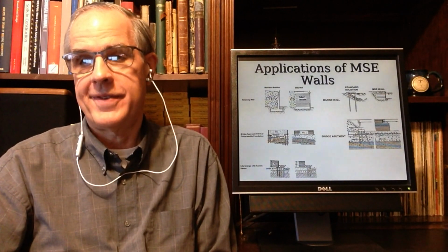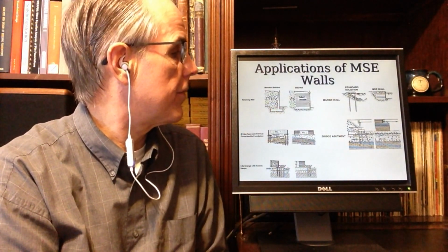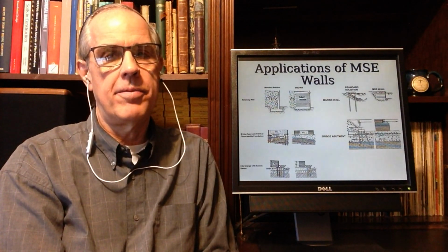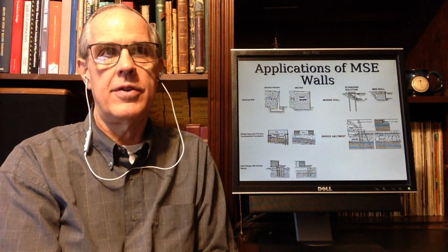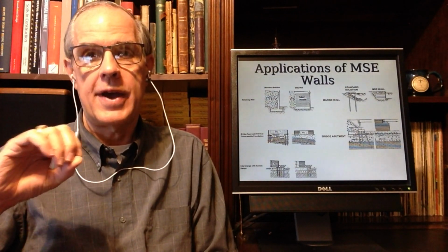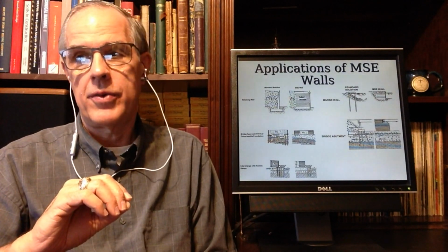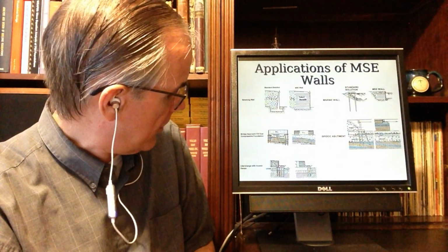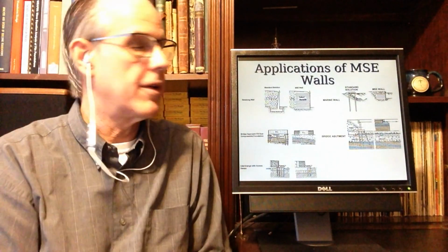Applications, of course, retaining wall. As you say up here, they can be used to replace gravity walls. Marine, I don't see that many marine applications. The biggest problem for using an MSE wall in a marine application is, it drains well. Tidal effects are not that bad. The biggest problem is going to be working in the wet, and you'll see that when we install them. You also have them for bridge approaches, interchanges like we talked about in Dalton, abutments and that sort of thing.